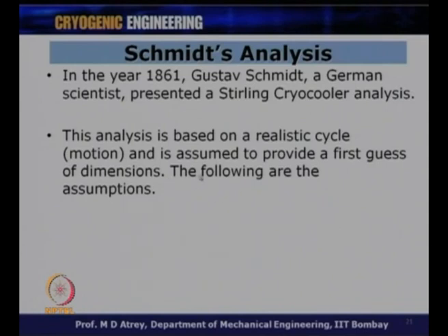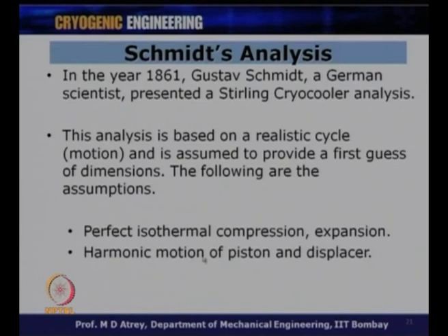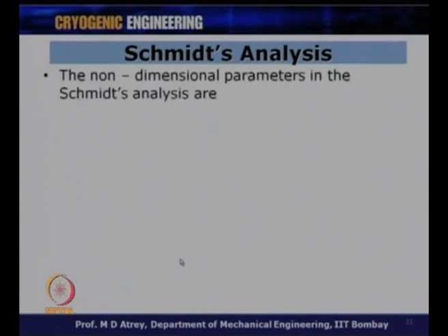The following are the different assumptions. He assumed perfect isothermal compression and expansion processes as exist in the ideal Stirling cycle. He assumed harmonic motion of piston and displacer, which is a more realistic motion. He assumed that there is perfect heat exchange in the regenerator. Also, he assumed there is no pressure drop in the system.